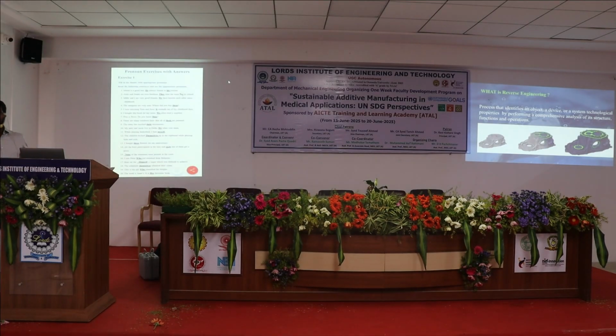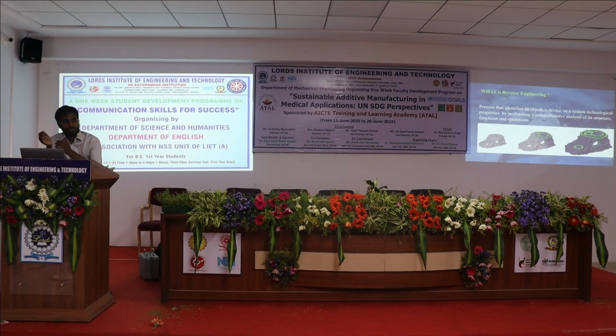How can you measure this mouse? Can you get exact dimensions with the calipers? When we have complicated designs with irregular shapes, then we go for 3D scanners. If you want to measure regular, geometrical shapes, then we go with measurement tapes, vernier calipers, depth gauges and so on. If we have irregular shapes like this mouse, car designs, bikes, everything, we go with 3D scanners.